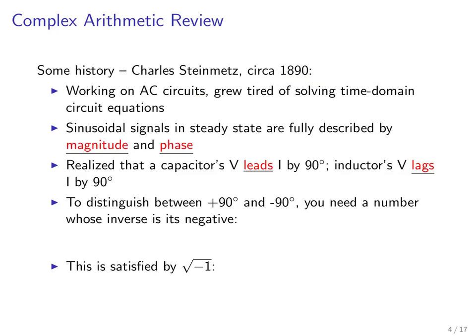time-varying signals. And he was getting tired of solving these time-domain circuit equations, involving all the derivatives with respect to time and doing all the calculus involved in that. And what he recognized, though, was that if he's inputting sinusoidal signals of one frequency or some small set of frequencies into his circuits and looking at the effect of the circuit on those signals, he could really describe that effect fully by characterizing what it did to the magnitude of each sinusoidal signal and the phase of each sinusoidal signal.